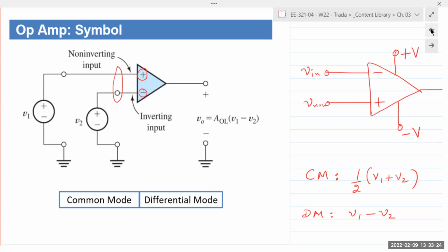The biggest example is noise rejection. In electrical engineering, any unwanted signal, any unwanted voltage or any unwanted current is referred to as noise. So even, again, using the microphone as an example, if the microphone is capturing my sounds, any other external noise should be rejected. And so to reject that noise, we use this kind of circuit, because if it's common, then it should be rejected. Yes, you have a question?